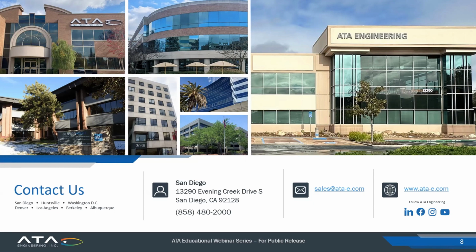If you just want to queue up jobs, you can use Analyze Multiple inside of Femap if you have the analysis sets set up. But it sounds like they want to change items each time, and we do have that ability in the API. You just have to have your application do event handling. I know that's a little bit more advanced, but if you have something that can do that, you should be able to monitor and track events.